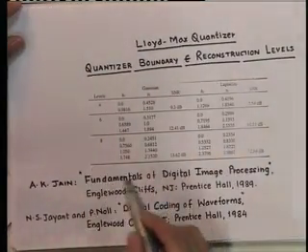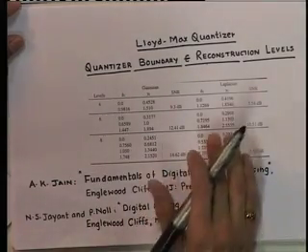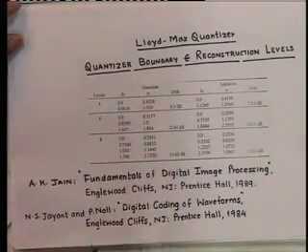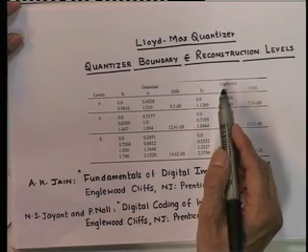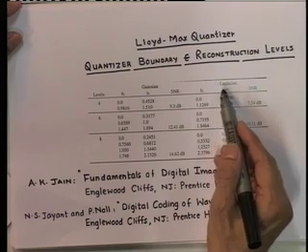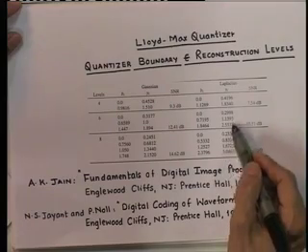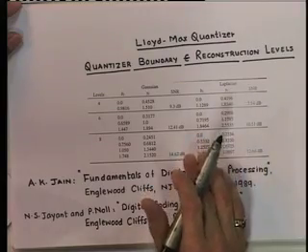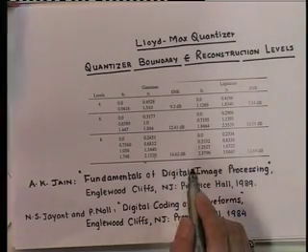Now, this table provides the decision boundaries and the reconstruction levels for various probability density functions and number of levels generated using the procedure just discussed. Notice that the input distributions that have heavier tails also have larger outer step sizes. However, these same quantizers have smaller inner step sizes because they are more heavily peaked.